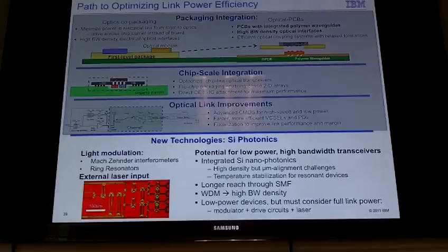So that's the Mach-Zehnder modulator. The ring resonator is a very compact device. It's roughly a 10 micron radius ring. It's a ring that's placed adjacent to a waveguide, and light can couple to the ring for a very narrow resonance. Basically, you have a notch in your transmission through the waveguide if you're at the resonance of the ring.